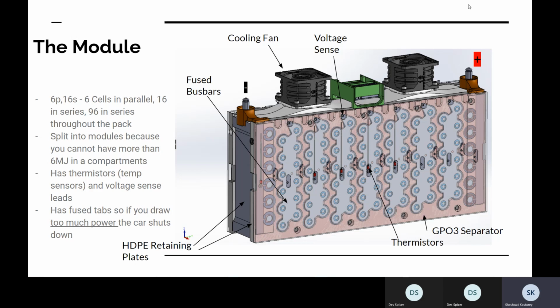So in the rules, there is some stipulation that says you can either directly measure the cathode or anode of the cells, or you can be like 10 millimeters away and measure the temperature of the bus bar, because the temperature of the bus bar is pretty close to the temperature of either the cathode or anode of a cell. You guys know what I mean by cathode or anode, by the way?